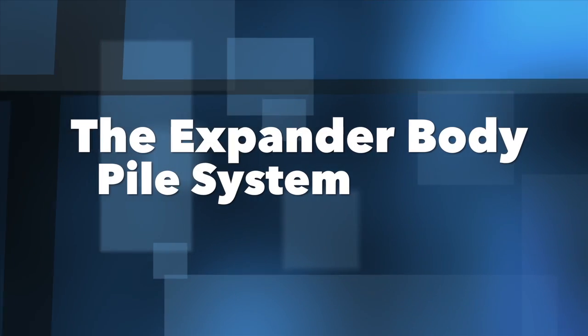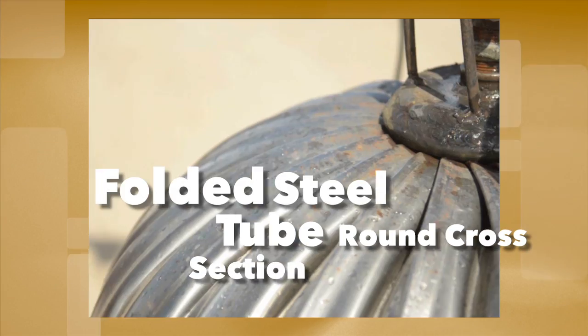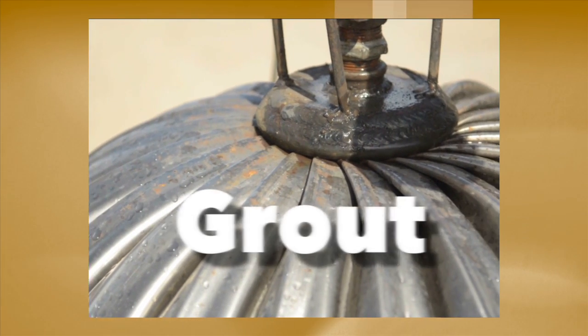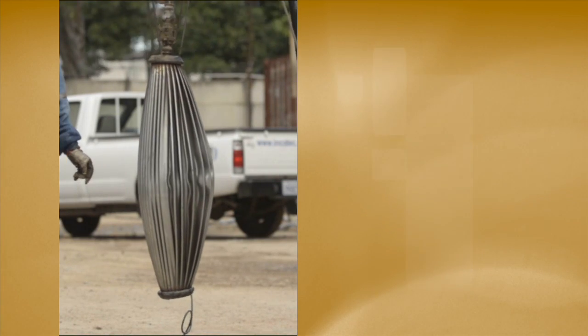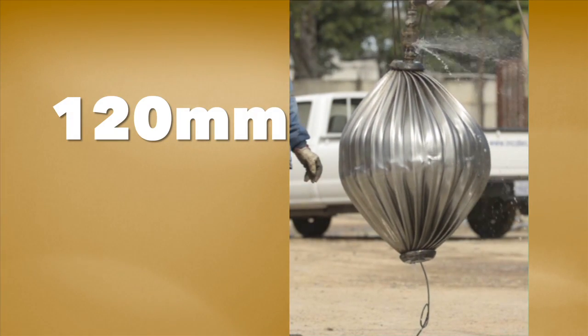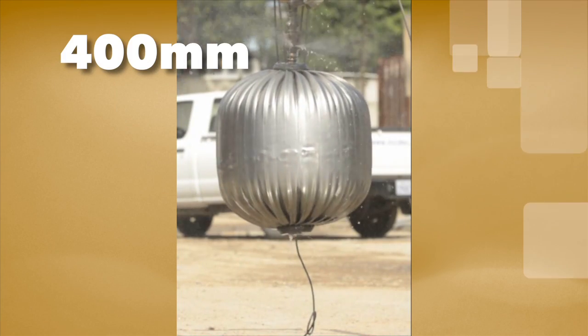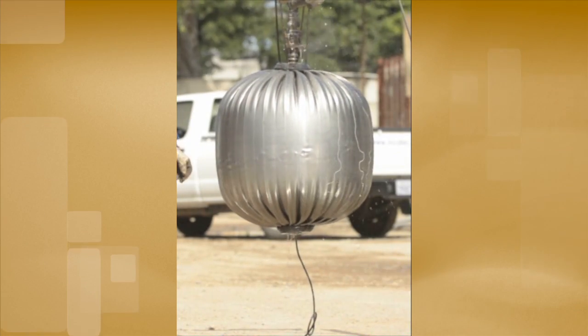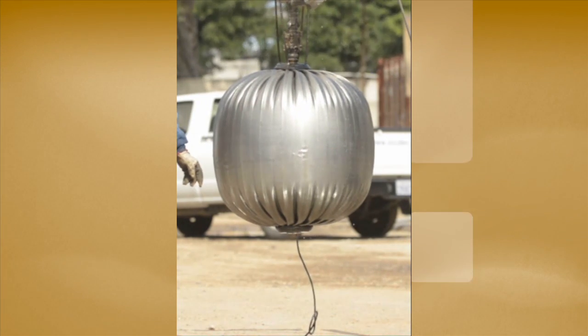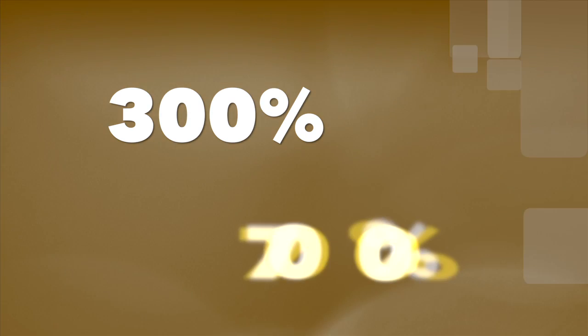The expander body pile system. The EB consists of a folded steel tube with a round cross-section. By injection of grout, the EB can be inflated, thereby creating a watertight steel cylinder of high strength. The EB diameter prior to expansion is approximately 120 mm but increases during the inflation process to between 400 to 800 mm, depending on the EB size. After expansion, the diameter of the EB has increased by about 300% to 700%, depending on EB model.